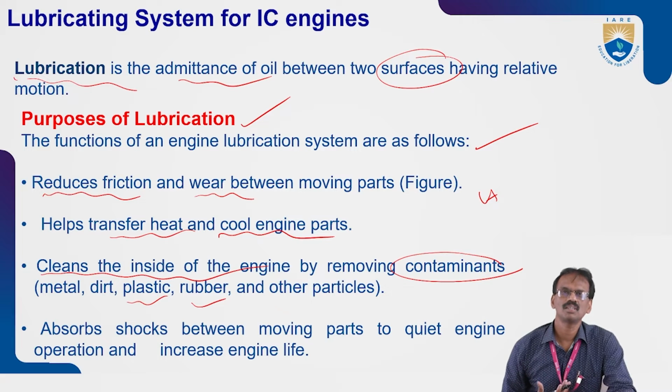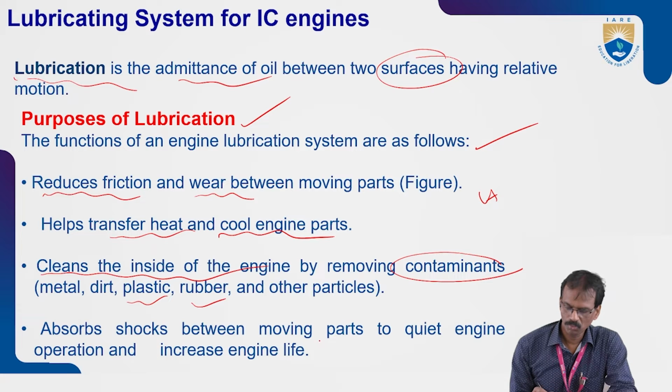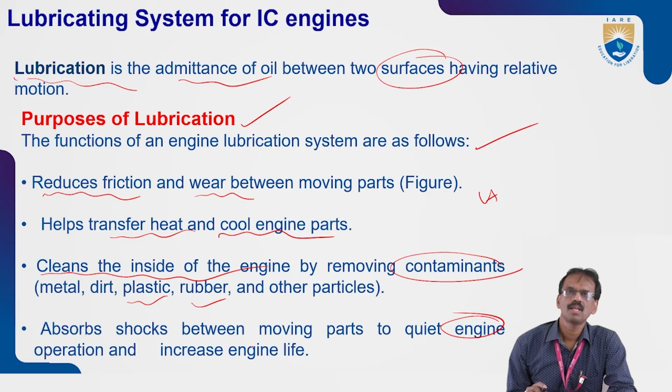Next, it absorbs the shocks. This is also very important. Lubrication absorbs the shocks between moving parts for quiet engine operation and to increase the engine life.